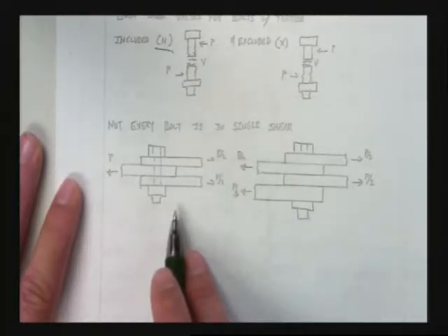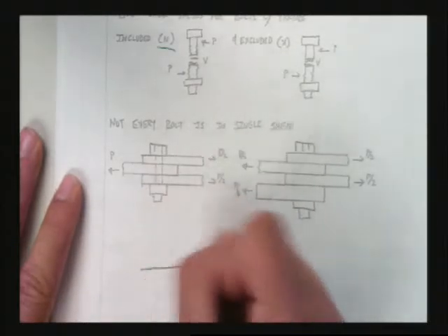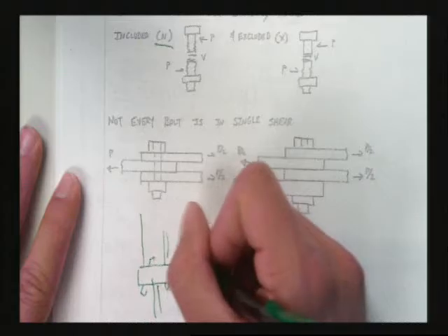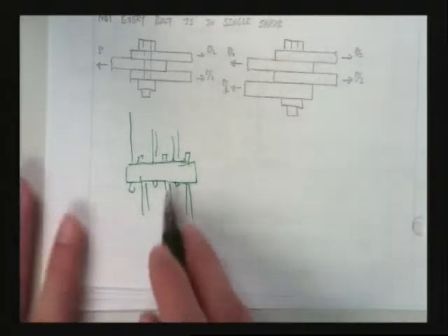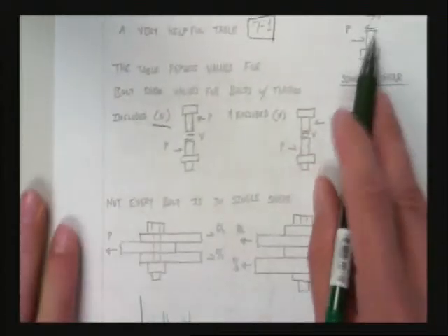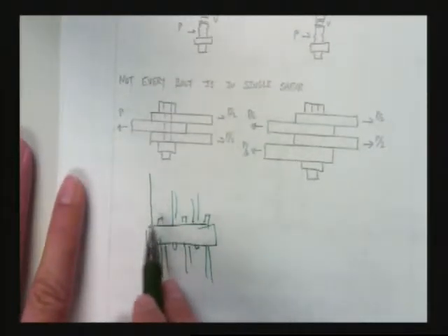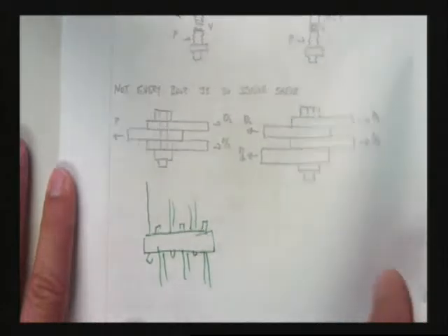If you're ever in Pittsburgh, or if you ever see these, there's these common types of trusses they used to build, and I can't remember their names right now, but they have these huge pins. And off these huge pins, they have an I-bar going one direction, an I-bar going the other direction, an I-bar in this direction, in this direction, over and over again. Why do they do something like that? It's so that they can take a pin, and instead of making the connection in one place and only having one shear plane, they can force multiple shear planes to happen. Right? So in a sense, by making these members smaller, they can also make their pins smaller, because they're spreading the area out where the shear failure happens over. Dividing and conquering. Well, that definitely looks like a good future homework problem for you guys to do. You can just see the scared look in the eyes.